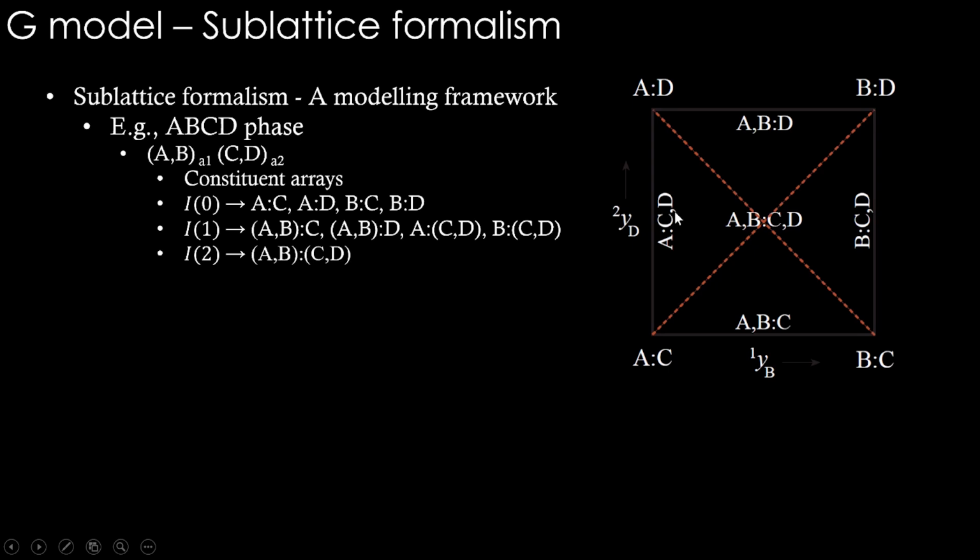Along this line, what happens is C and D both mix in the second sublattice. So various compositions of C and D can come from here to here, reaching 100% D here in the second sublattice. Okay. Similarly, all these edges are going to represent mixing in one of the sublattices. And the red line here is going to represent mixing in both the sublattices. If you see here, AD is here and AD becomes BC. Therefore, in the first sublattice, A is gradually replaced by B across this line, and D is gradually replaced by C across this line. Therefore, eventually it becomes B colon C.